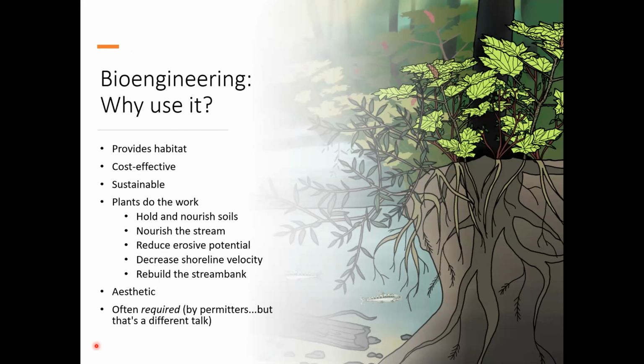Next slide, please. So here we list a few advantages in using bioengineering. In both the short term and long term, bioengineering provides habitat for all manner of terrestrial and aquatic life. I think a good context for this was provided yesterday in a couple of the talks. By and large, bioengineering is more cost effective than hard engineered solutions, primarily because most of the techniques don't require heavy equipment, but also because many of the vegetative materials can be sourced or even collected locally.